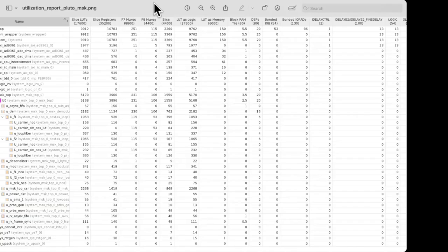But when we talk about how much Opulent Voice really consumes, our custom logic that we have put into the reference design from Analog Devices on the 7010 for the Pluto SDR is about 5,000 LUTs. Now, when we talk about the AMSAT UK effort and the MDT project, or Mode Dynamic Transponder, with an ICE40, it's around 5,000 LUTs. You don't ever want to get to 100%. Designs never actually use 100% of your resources, because weird things happen.